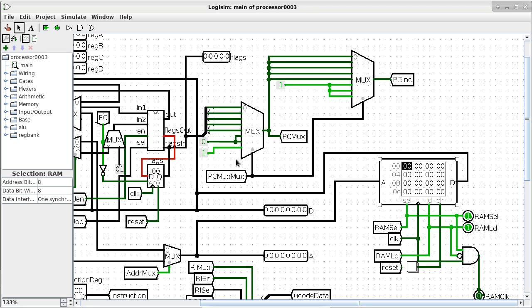Okay. So if you go back to here, there are only 3 attributes associated with RAM. The third one, we are not going to deal with it, okay? So it is basically synchronous, and we'll just stick with that. The first 2 have to do with the width in terms of number of bits associated with the A port, the address port, and also the D port, which is the data port, okay? So what that is going to do is you can control the width of the A port. That determines how many locations we have on this particular RAM component.